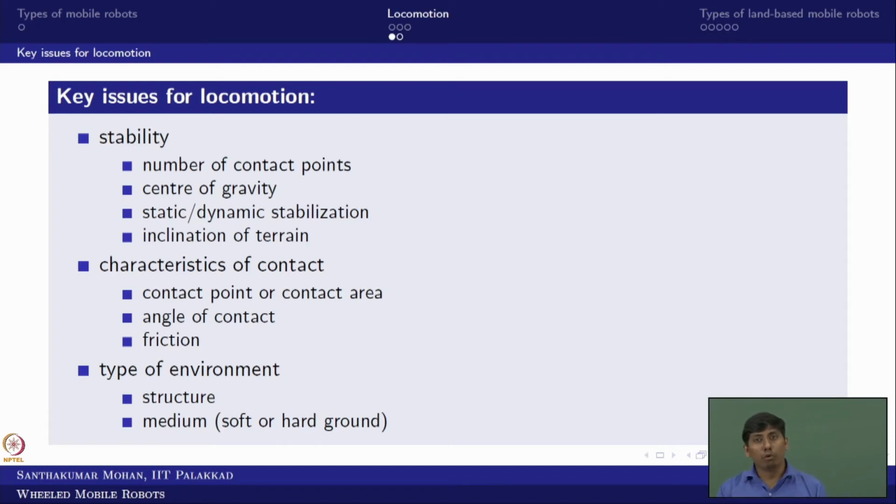When you take a stool with 4 legs, which is more than 3, if you cut a small portion of one of the legs, you can see a zigzag motion. Although it is statically stable, the motion is executed. So the minimum number of contact points required for static stability is 3, but if you have more, then you have to provide proper contact ensuring points.